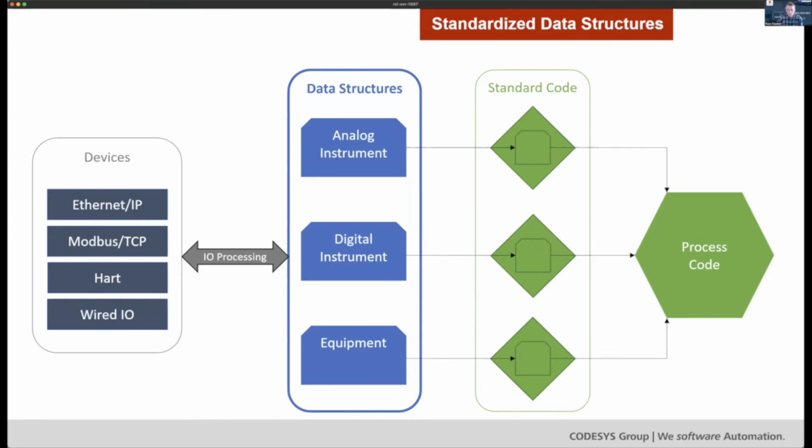And then we have a digital instrument of some kind, typically a switch. In the water world, it's water on floor, or maybe an intrusion switch to say that somebody opened the door or something like that. Just an on-off digital instrument, right? And then lastly, we have equipment. Now, equipment is pretty broad. This is valves, pumps, VFDs, a generator, things like that. Anything that we control, any kind of moving object, so starting and stopping a VFD or moving a valve, something like that.